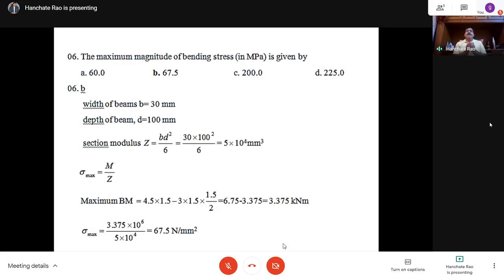In sagging bending moment, above the neutral axis we get compression and below it we get tensile stresses. In hogging bending moment, above the neutral axis we get tensile stress and below it compressive stress. At the neutral axis the stress and strain are both 0. The neutral axis undergoes neither elongation nor shortening.